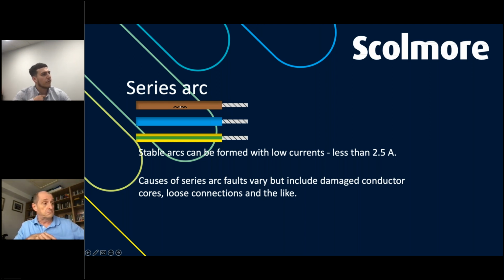Yeah, so the types of faults that they're looking at, as we've already mentioned, is in one single conductor. We're not necessarily just looking at the parallels now. This is something that we've not seen before when it comes to looking at faults. So it's one single conductor. Probably prudent to mention ring final circuits at this point, suggesting that actually you can't get the fault that is needed, that high resistance joint, to generate a series arc when it comes to a ring final circuit.